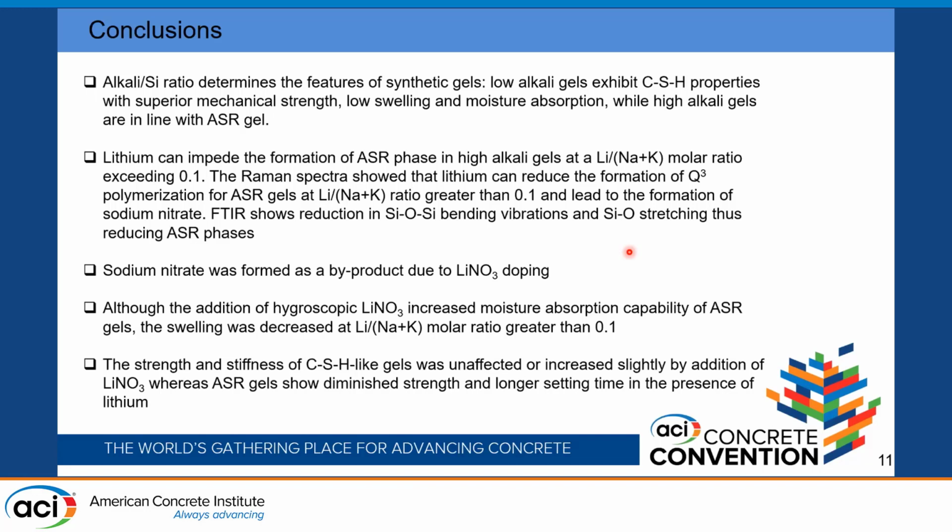Now, lithium nitrate can delay the formation of the ASR phase in the high alkali gels with a lithium to alkali molar ratio exceeding 0.1. And the Raman spectra have shown that the Q3 polymerization, which is mainly responsible for the swelling and moisture incorporation, is reduced by the addition of lithium nitrate beyond 0.1 molar ratio. And also the FTIR results have shown that it is capable of reducing the intensity of the ASR-like phases.